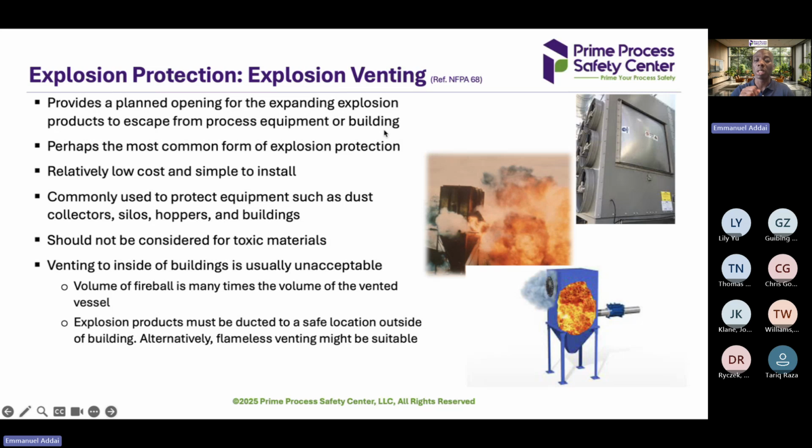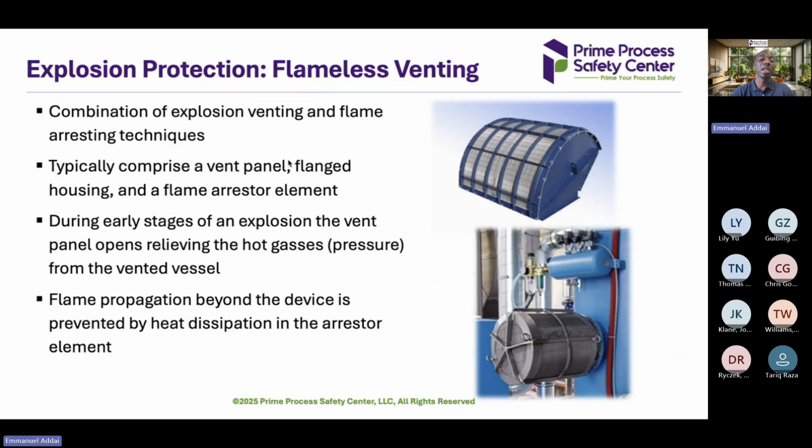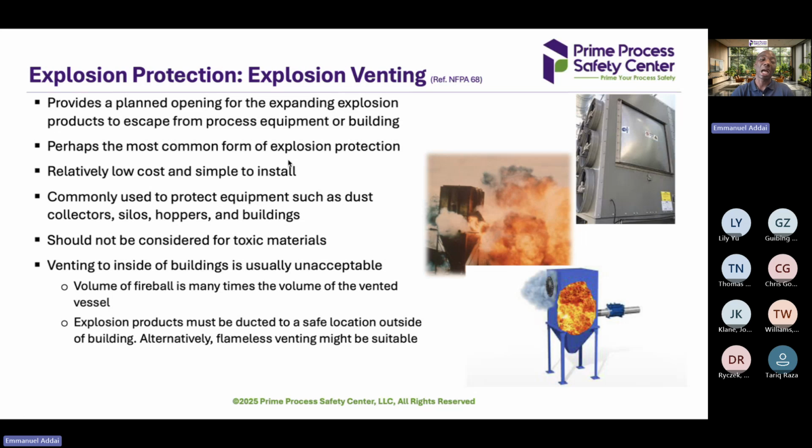You can see on the top one a low pressure rated aluminum panel, and in case there's an explosion, it will open or burst, and the pressure will move out from there. Otherwise, you see the picture on the left, there was total destruction. So you always need to have an explosion relief vent for your equipment if it is prone to explosion. If the equipment is located outside, then you can use the explosion relief vent.